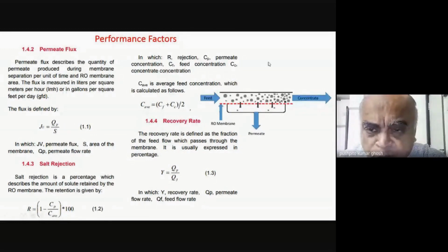Firstly, what am I doing? Usually, the process is done with what is known as a cross flow. That is, I'm passing the feed perpendicular to the direction in which the permeate water will travel. So this is my membrane. I'm passing the feed in this direction, and the water is basically coming here, my permeate, and it shows that it's never a 100% rejection.